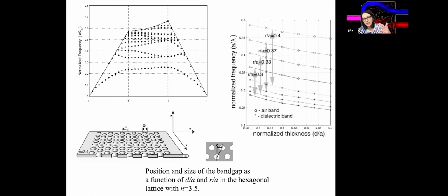So when you look at the photonic crystal pictures that I showed you before, they generally have a thickness of around 200 to 250 nanometers if they're built for operation at telecommunication wavelengths. So that's the rule of thumb. You want to be in the single mode regime vertically. If it's not in the single mode regime, all of these modes that you produce in the photonic band diagram originate from slab waveguide modes, right? Just folded back by the symmetry of the holes that you etch in the photonic crystal.